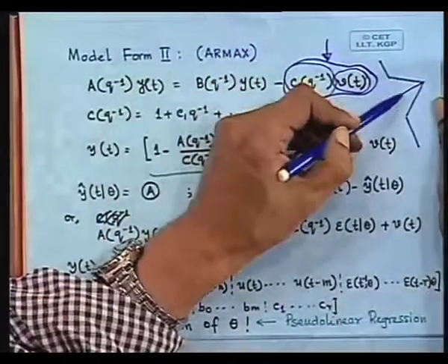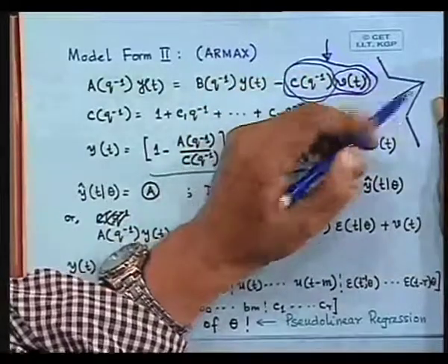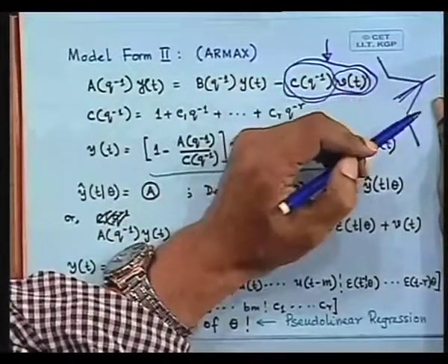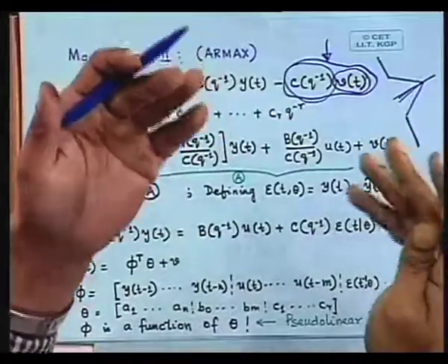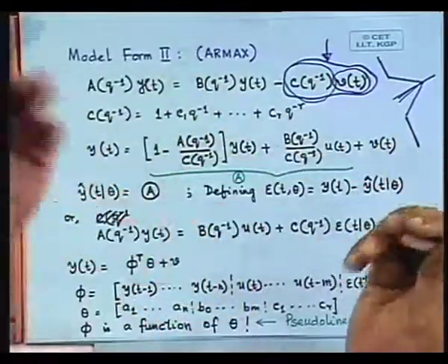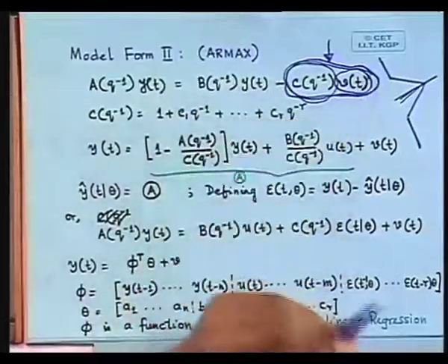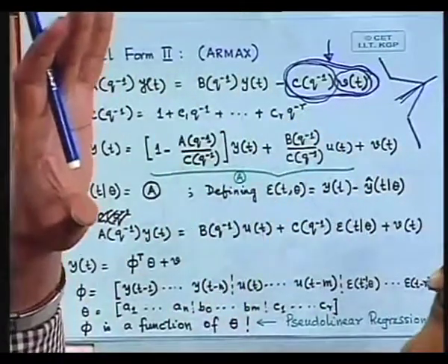So now your autocorrelation function is going to spread. It is not ideally white. It may be correlated with the past sample, but it will obviously not be correlated with 30th order samples maybe. So you have relaxed your noise model assumption because you found that the previous model does not work.